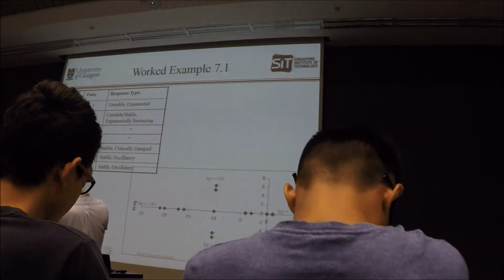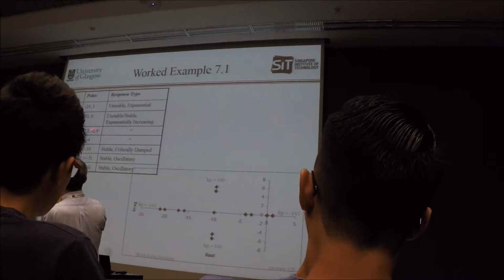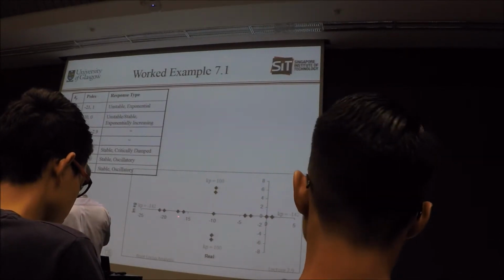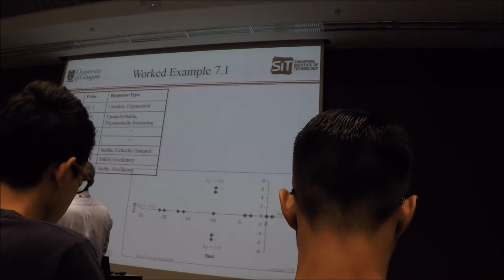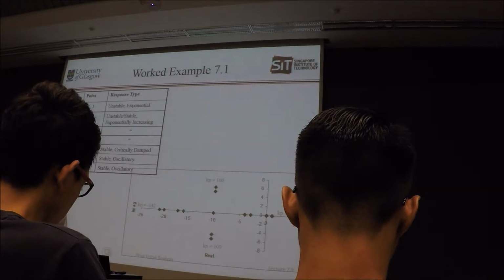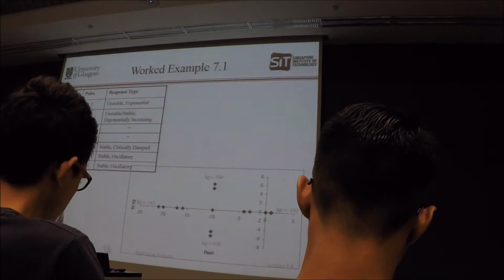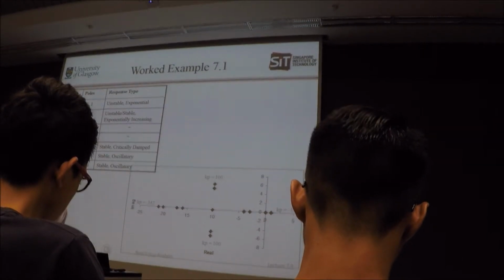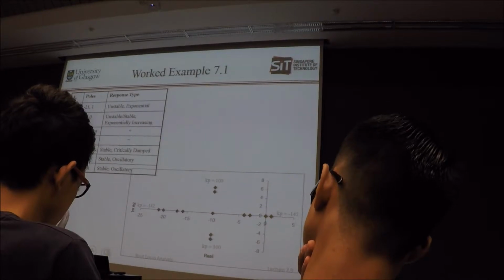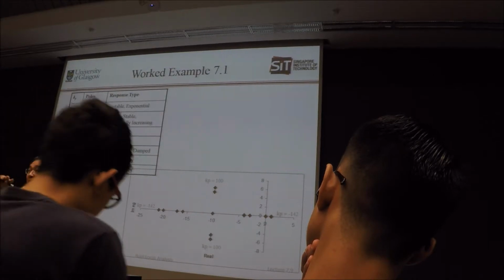When you set Kp equal to 0, you have poles at minus 17.1 and minus 2.9. So your response will be stable, right? Because both poles are in the left half plane. You can see that your response is going to be exponentially decreasing. In the way that if you have a step input, it's going to be like a step response: two first order steps superimposed onto each other.